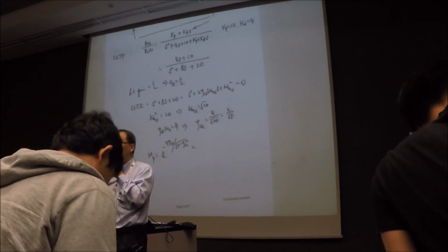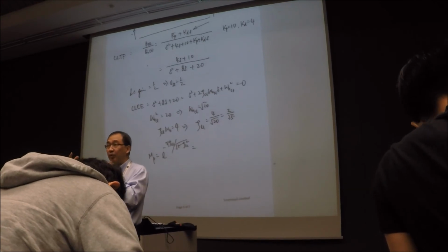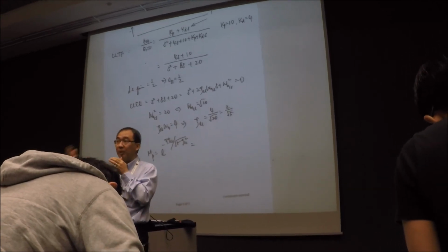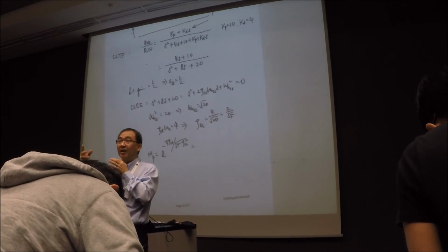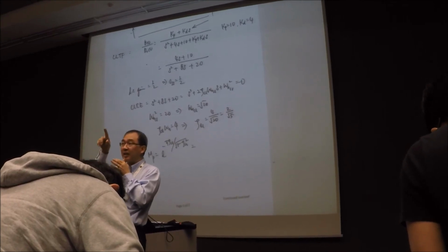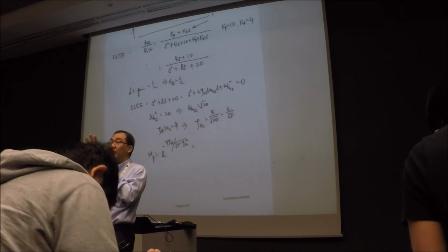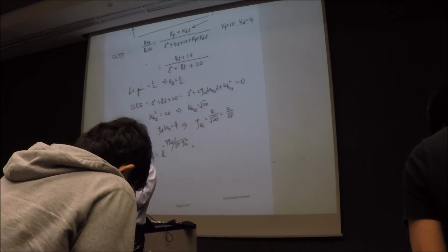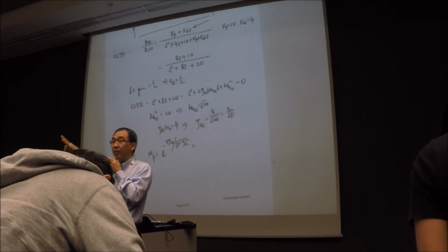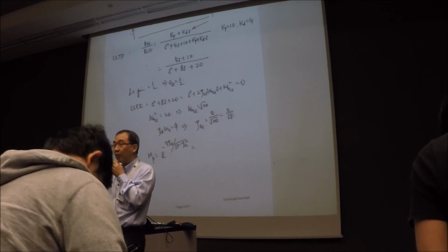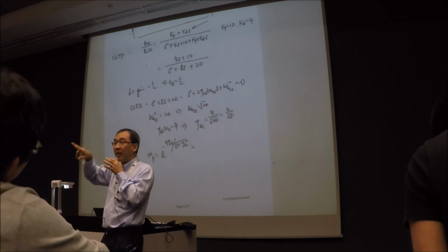As we mentioned, if you were given maximum overshoot, straightforward, you can work backward to get your undamped natural frequency. And then from there, you say, okay, this is my 2 zeta closed loop omega n closed loop, the first order term. From there, you can work backward to find out what is your undamped closed loop natural frequency, omega n CL.